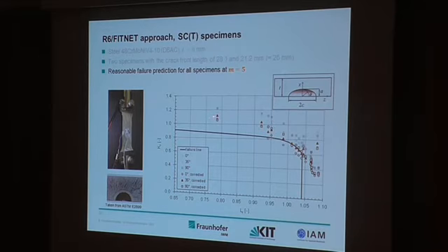And what one should assume, or imagine, is the upper bound curve coming from the most loaded point, and you see that we are able to describe all these results in a better way and still in a conservative way, even if some points are below the failure line. But this is the point governing fracture, this one, and so on.